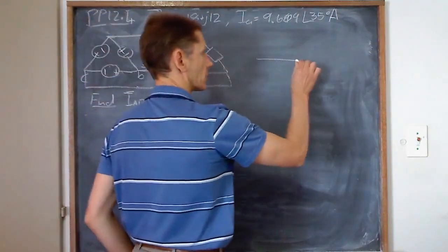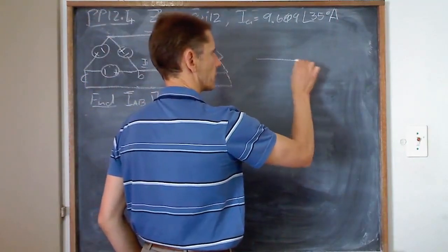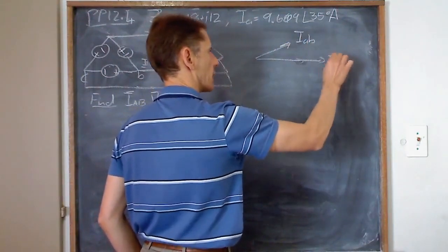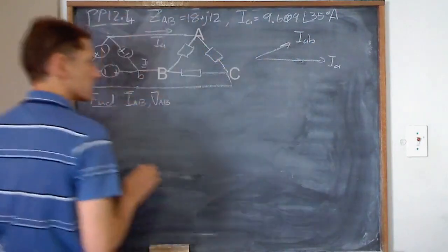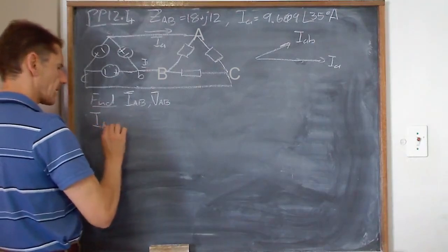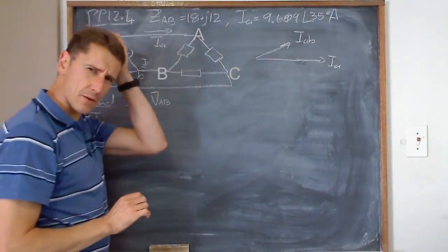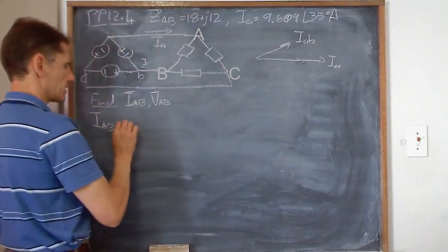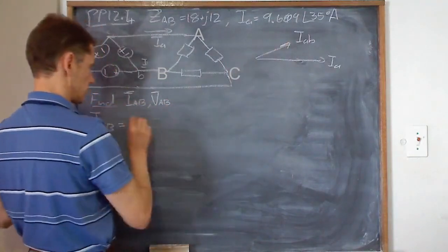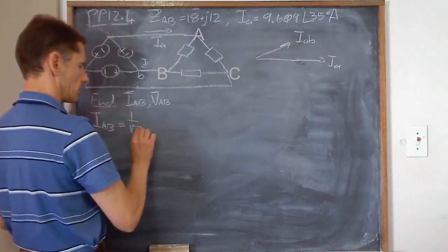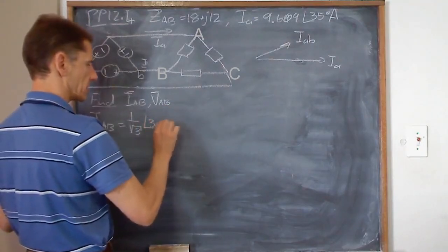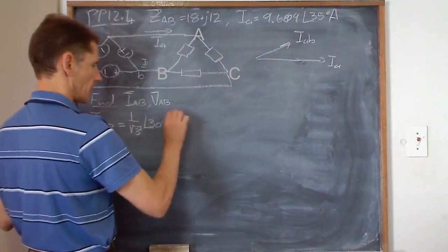So that's now the second little triangle that we did for the currents. So you've got IAB there, and you have IA over there. So what do I need to do with IA to get IAB? Capital, uppercase, lowercase, that obviously doesn't matter now. It's the principle that applies. What do I have to do with IA? I have to make it smaller, so I have to divide it by √3. And then I have to add 30 degrees to my IA.